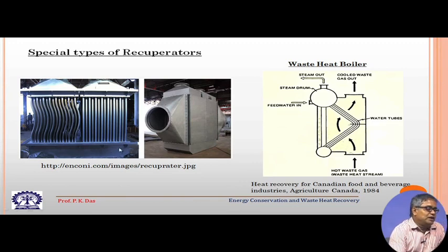Through this tube generally hot gas passes, and across the tube the cold gas or cold air passes. So, from the furnace, from the incinerator, the hot gas will come and pass through this tube, and outside there will be the cold gas that will pass. These are bare tubes, sometimes they could have some fins depending on the type of gas we are using, and these are specially used for waste heat recovery.